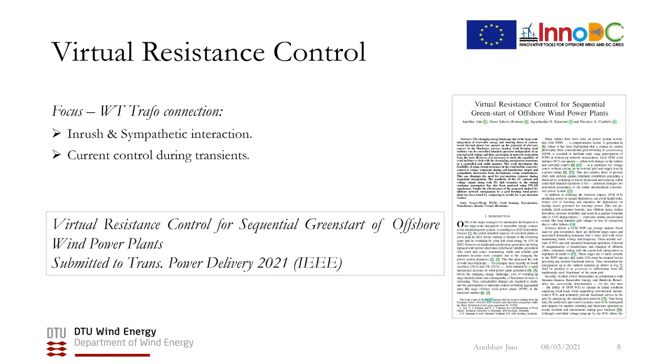Recently, we have submitted a paper investigating how virtual resistance control can be used as an alternative to the traditional current control loop to deal with inrush current limitation during wind turbine transformer energization and limit sympathetic interaction between downstream string transformers. This mimics the physical soft starter used in old fixed-speed wind turbines and can help avoid the use of a pre-insertion resistor while allowing higher robustness from hard switching.